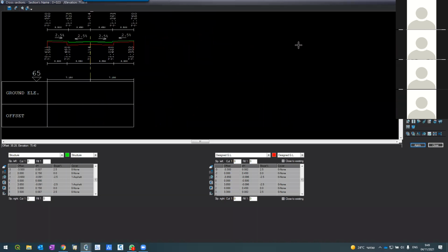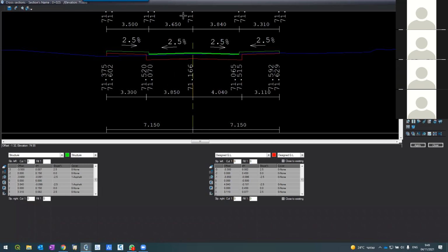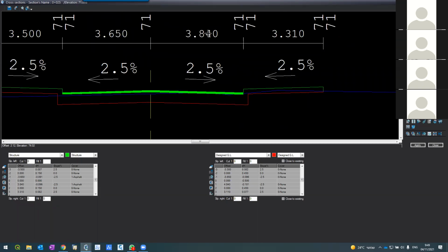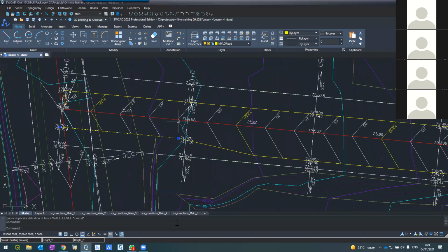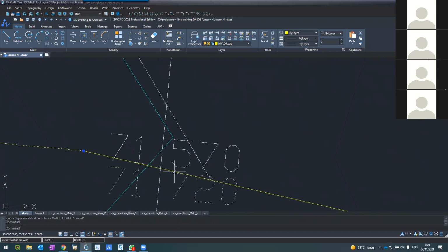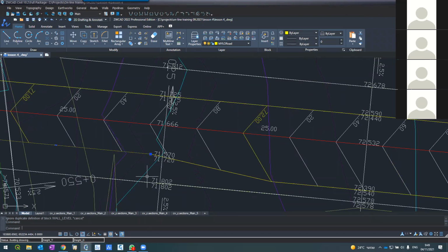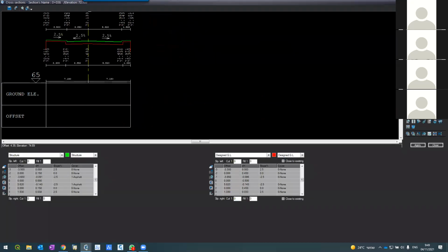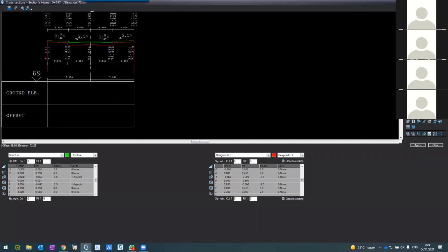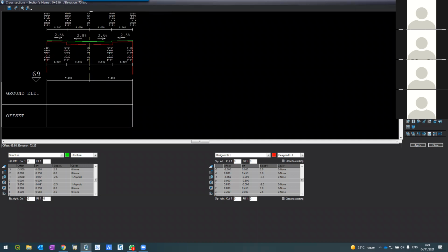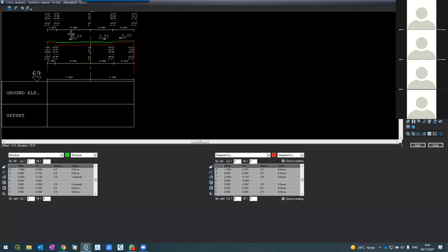It digitized a section here for the beginning of the change, because this section 25 is already wider, right? See here what's happened? It's in the middle, it's here. It's already wider. It's not 3.65, it's 10 cm wider. So the software created a demi section here. You can see it here, and the same one here, and the same one here. All the breaks, when they start to be breaks in the section, it created in the layout demi sections.